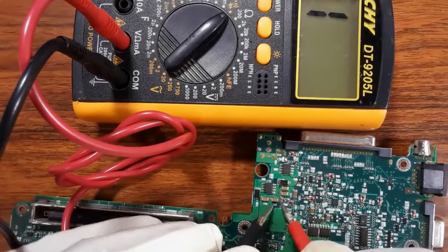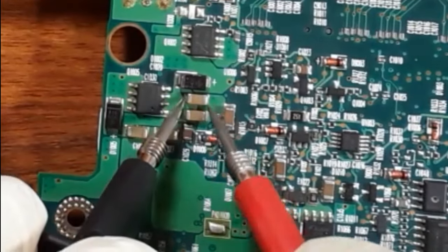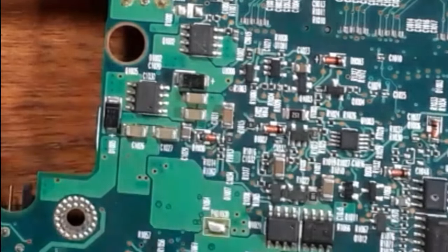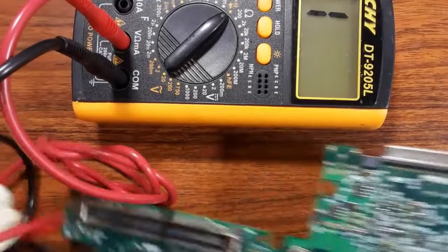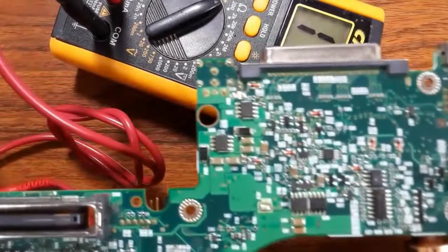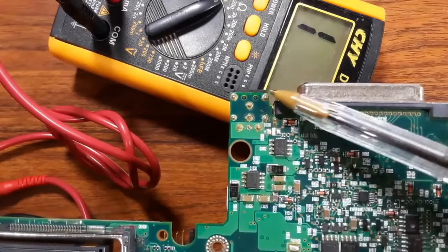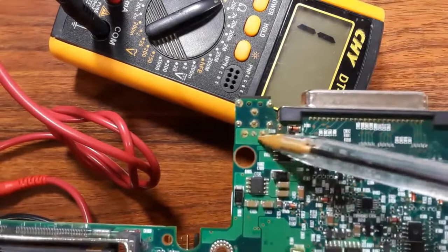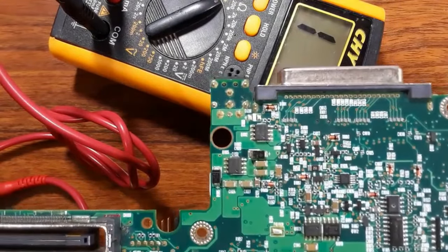So here we have PF capacitor. The PF capacitor, you should note here no buzzer. So all these PF capacitors are good. As you see, we have checked about all these components, and it seems that all these components are in good state. Now the power jack is good, the solder of the power jack is good, these components are good. So let's check another motherboard.